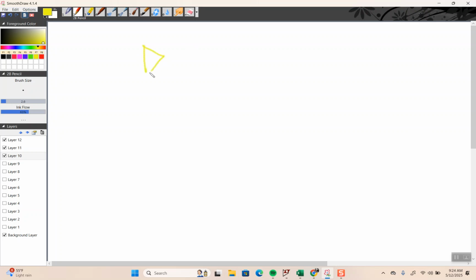I can have an op amp, a two-stage op amp with some kind of Z network, right? Which could give me a low pass with a gain or just a gain, plus or minus. And to be able to work that out and then come up with a Bode plot, right?